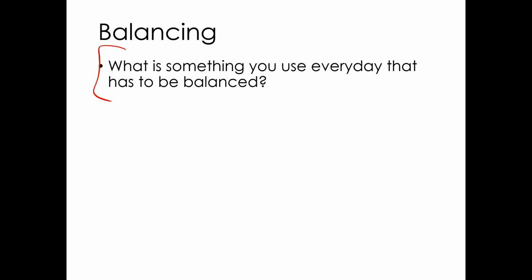Now in vehicles, I've driven a lot of race cars that have tires that aren't balanced, that run at a relatively low speed, things like Formula SAE cars. In that case, we never really balance the tires, and it's not that big of a deal, again, because of that omega squared thing. So if you tried to run a regular vehicle, your car or truck or something, unbalanced, you put the tire on the wheel and drive around, in most cases it would probably be okay, and it might just be a little uncomfortable at higher speed and vibrate a bit. For really big imbalances, like really big tires at low pressure, it might be more of an issue, and instead of being an inconvenience or annoyance, it might actually end up being a safety concern.